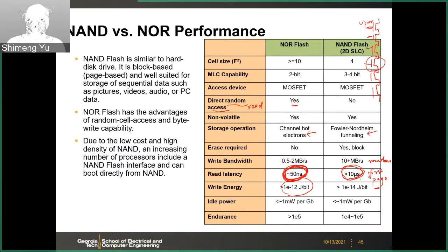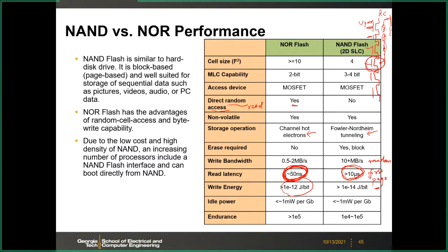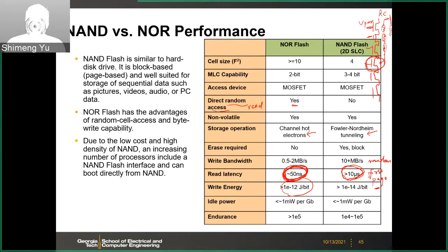So the current will go through the series of those channel resistances, and then to the BL, you have BL cap. So there is an RC delay from this selected cell to your sense amp. So the series resistance from the drain will limit your RC readout performance.